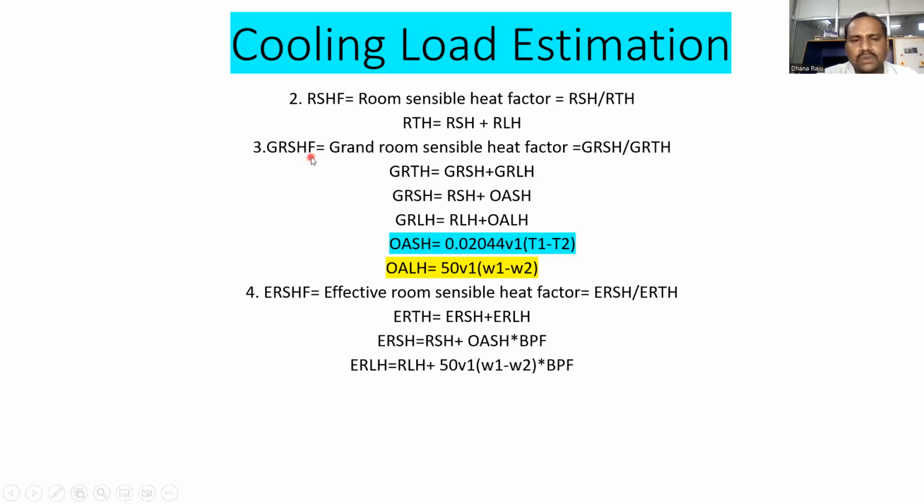Then grand room sensible heat factor. What do you mean by grand room sensible heat factor? If you consider the infiltration load, then it is called the grand room sensible heat factor. For room sensible heat factor, we neglect the infiltration load. What do you mean by infiltration load? Whenever the door is open, outside air enters the room, which increases sensible heat as well as latent heat. If you consider that, then the room sensible heat factor becomes the grand room sensible heat factor.